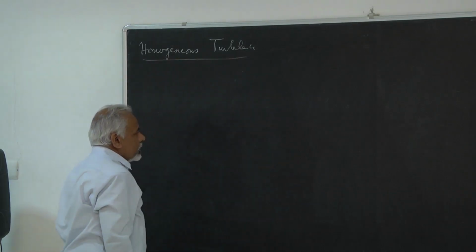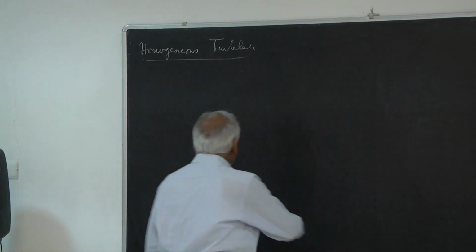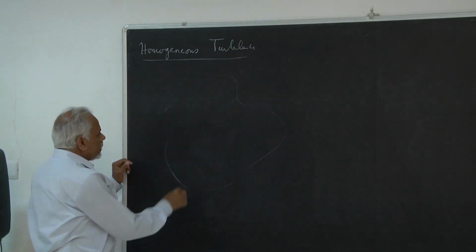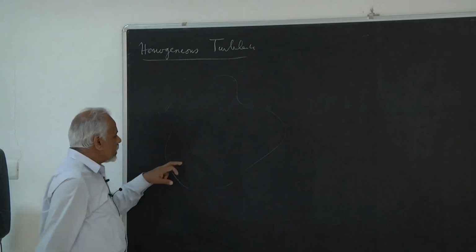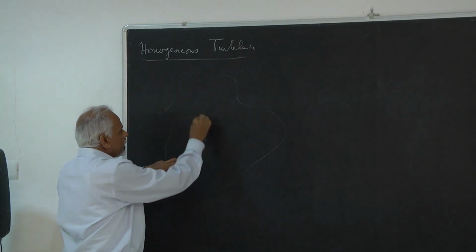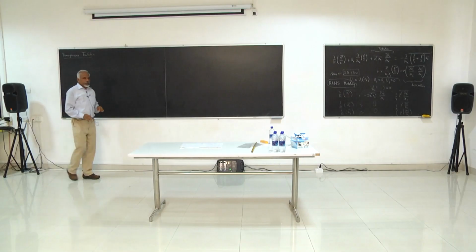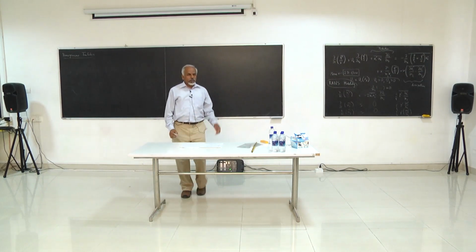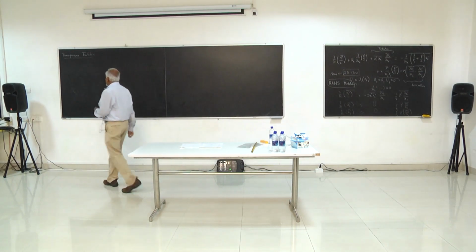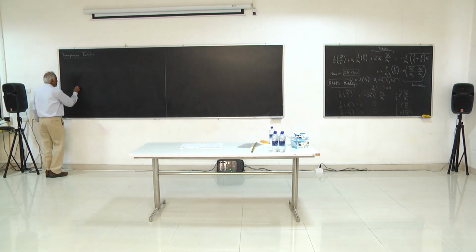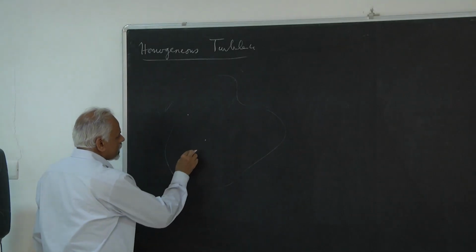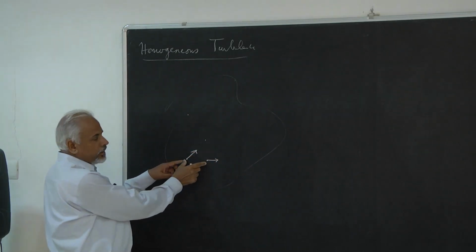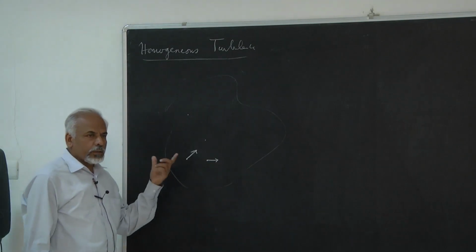So I have a case where, let's say I have a turbulent flow somewhere. If I made any statistical measurements here and here or anywhere, they would all be the same. So the translational invariance of single point statistics. Not only single point statistics, for example, if I took one velocity there and another velocity there, and I computed their average, time average.